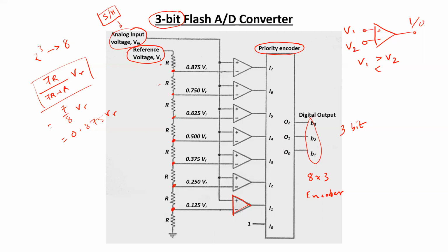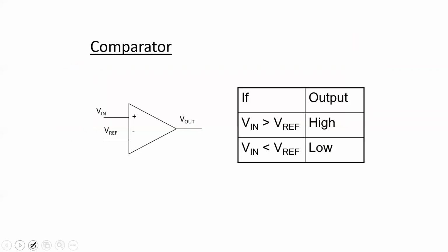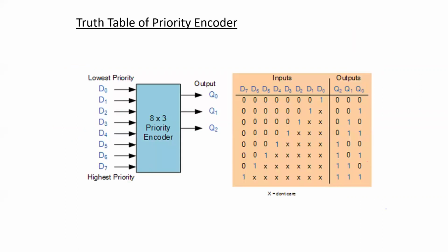Yes, that is the case with priority encoders. So the truth table will be much easier to demonstrate. Like your friend suggested, whenever a higher significant bit is 1, then for all the lower significant bits, the don't care condition will be considered, if no other higher significant bit is equal to 1.